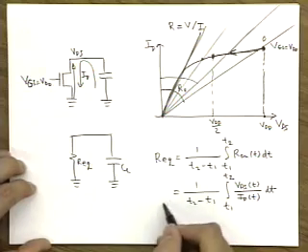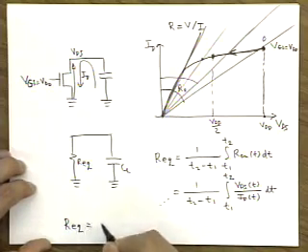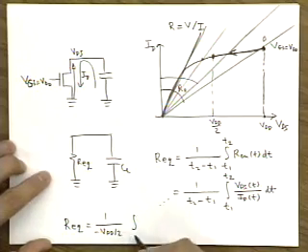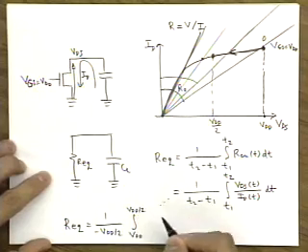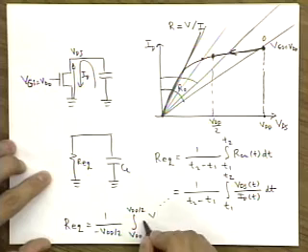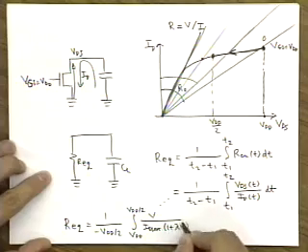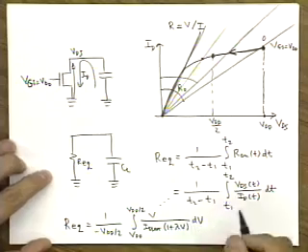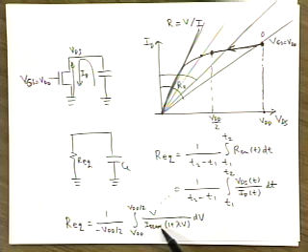So then you can solve for this expression, and you end up with minus VDD over 2 when you integrate between VDD and VDD over 2, and then you have voltage divided by ID sat times 1 plus lambda times V dV. Now in order to obtain the resistance, you need to make an assumption about the mode of operation so that you can choose the appropriate model.